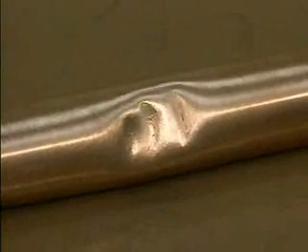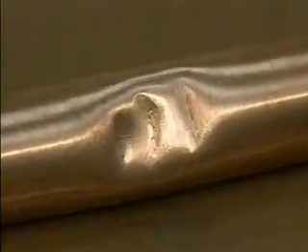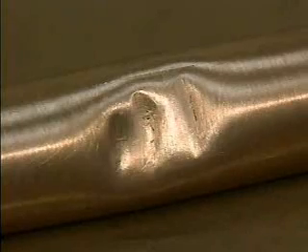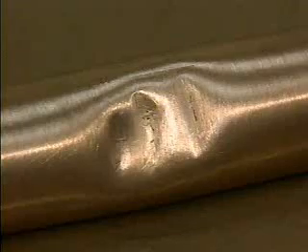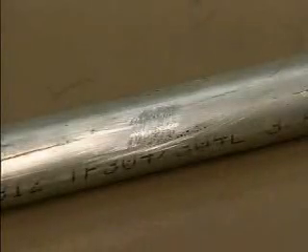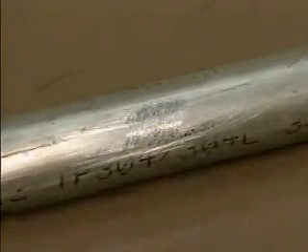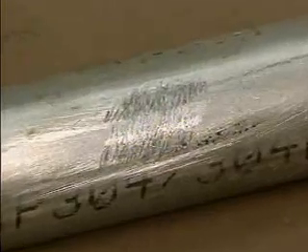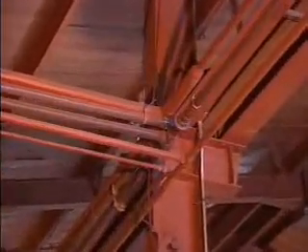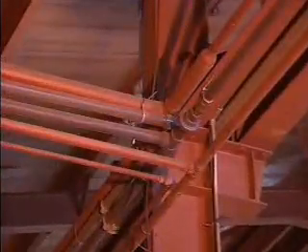Another common type of damage, dents, can diminish the strength and capacity of a pipe. Dents can be caused by mishandling pipes or improperly storing them. Replace dented pipe as soon as possible. During a pipe inspection, it is important to check pipes for signs of wear. Shiny spots on a pipe are common signs of wear. Providing additional support or protection to the pipe may be necessary to prevent additional wear.